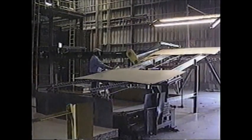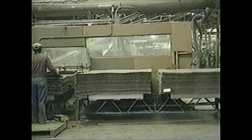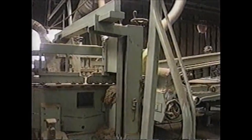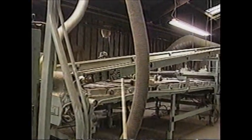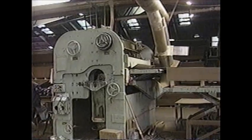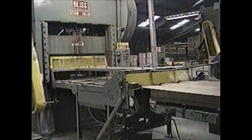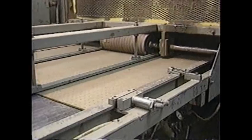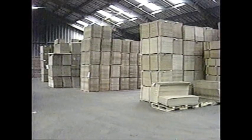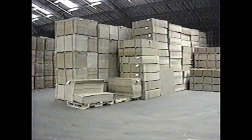Panels are graded by inspection of the top surface after emerging from the conditioning tunnel and are sorted into 2 grades. The graded panels are then trimmed to finished size. The trimmings are chipped and used as boiler fuel. After trimmings, graded panels are sanded to obtain a finely finished surface. Some of the plant's production passes through a perforating press, which punches 3 rows of holes simultaneously, producing pegboard. Several sizes, grades, and types of hardboard are produced at Conway, a good example of a plant manufacturing a quality product from a neglected source of raw material.